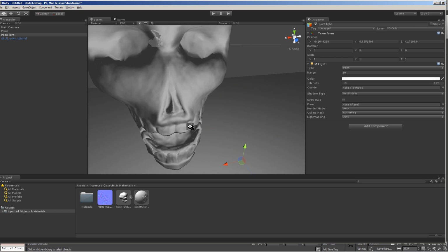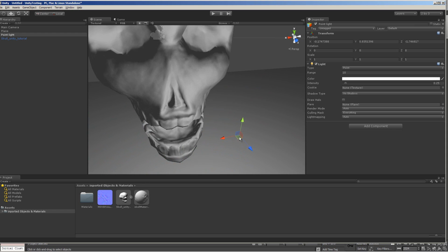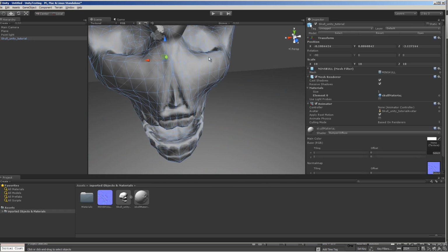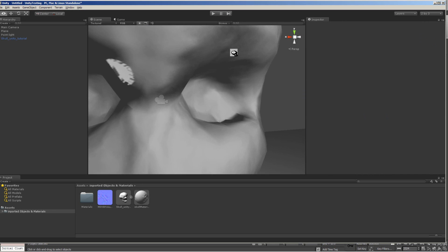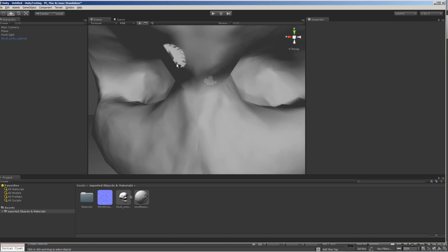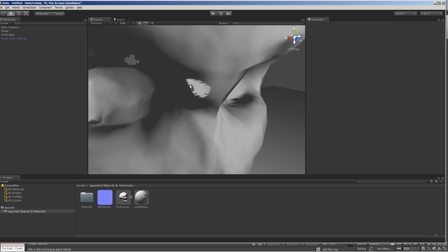So if we come closer to it and change the light, we will see that the shadows follow the light very nicely, although there are not many polygons on the model itself. You can see that there was a problem with the normal mapping over here, so in 3ds Max we should have checked the cage at this point right there, and we wouldn't have this kind of anomaly. And this is exactly the red spot on the texture that 3ds Max indicated.